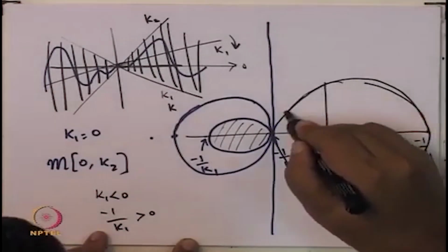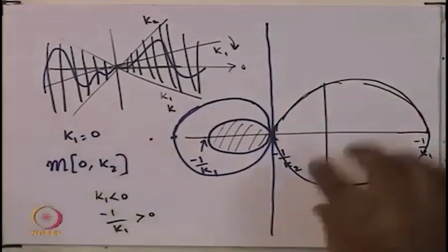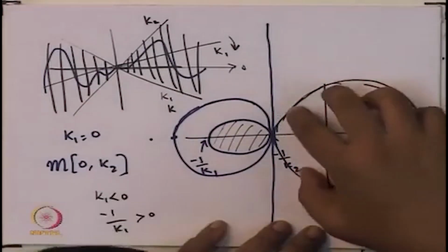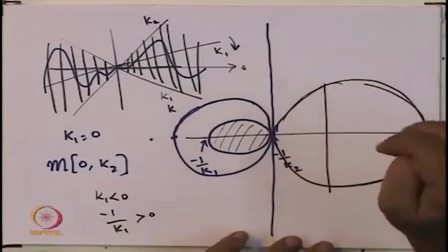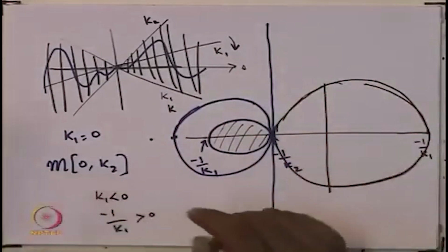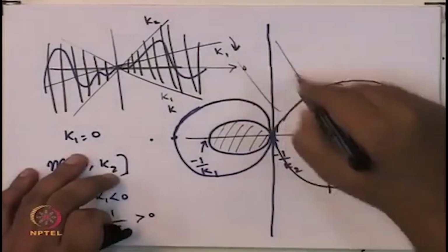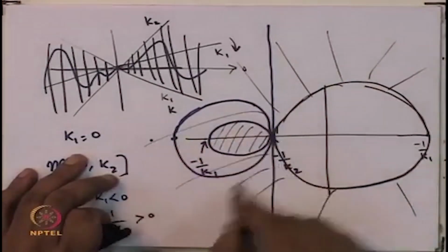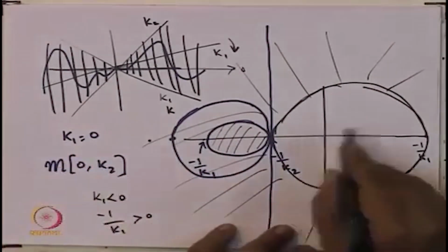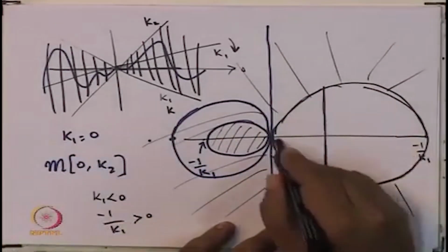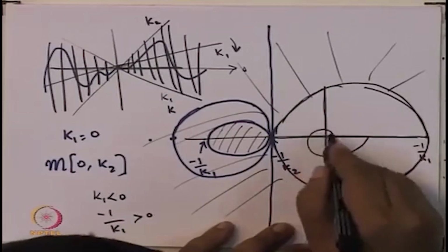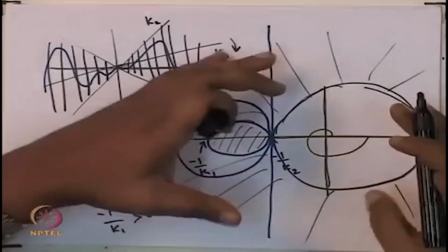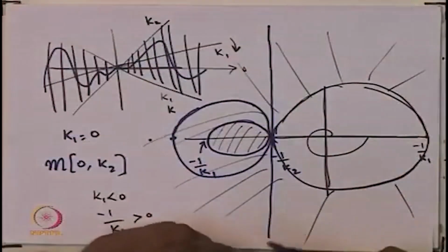You get a circle like this, but there is a catch. It turns out that now the bad portion is the outside of the circle. In other words, the Nyquist plot should lie completely within this region, and anywhere outside is the forbidden region.